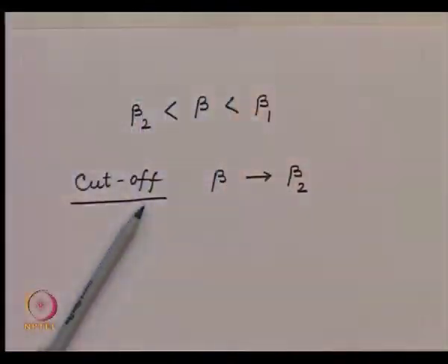So essentially the limit of beta 2 and beta 1 is telling us that the energy is there in these two regions, and because the energy outside the core has a tendency to travel with phase constant beta 2 and energy in the core has a tendency to travel with phase constant beta 1, there has to be a mutual agreement so that they can travel with a phase constant which lies between these two limits.